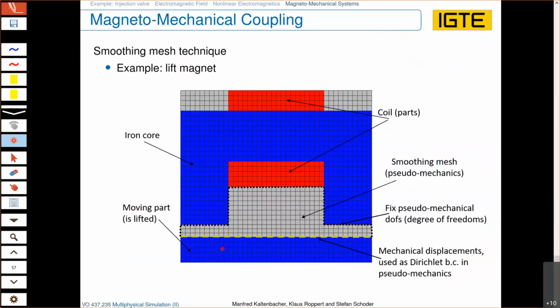But then you have a problem, because what we get out is, in these nodes along the yellow line, we get new mechanical deformations, and that we add to the coordinates. But when we add it to these coordinates along the line, after some time the coordinate here will have a larger y value, so this is x and y, as the coordinate of this finite element. So this coordinate would be larger than the coordinate of this node. That's not possible. In practice, you would get a negative Jacobian when you compute the entries of your system matrix. Okay, so the simulation program will break down.